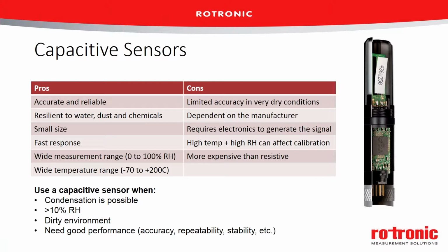So there are capacitive sensors set up to measure as dew point measurement devices, and they'll measure from very dry dew points, even down as low as -70, -80 dew point, and then up to about 10 or 20 degrees C dew point, depending on the sensor. So you can get them set up for measuring either the very low water contents or the higher ones.